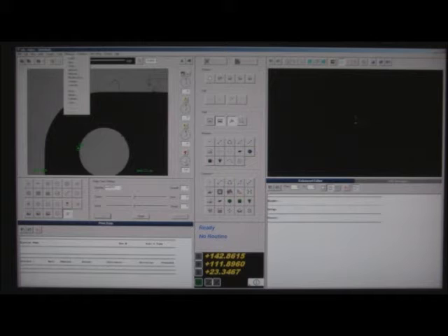If we go back to measure quickly, I'm backing up here, and again, these icons we're going to see over in the measure icons here. And we have point, line, circle, distance, midpoint, which is symmetry, min-max average, contour, and centroid. And then we have the 3D features. Again, the 3D features can be measured with the touch probe, certainly. We can also measure a plane with the video focus or measure a plane with the laser. We can measure a sphere with the video focus or the laser. Cylinder and cone predominantly require you to use the touch probe.